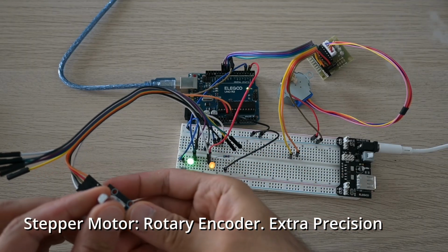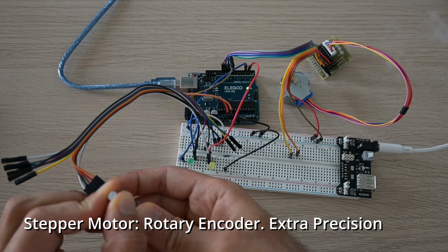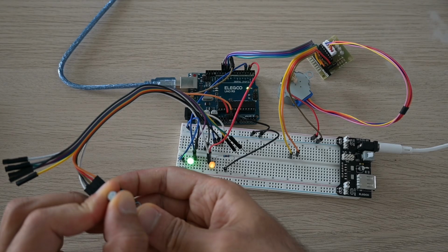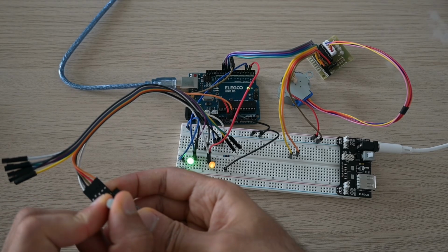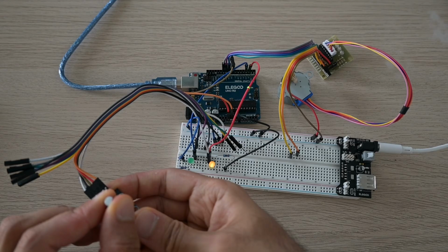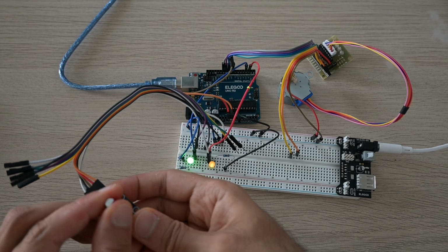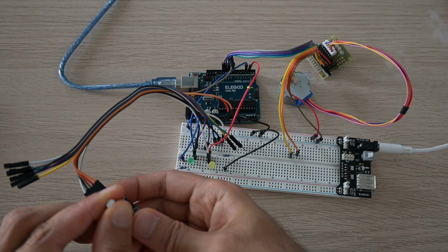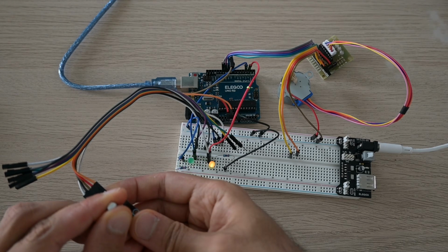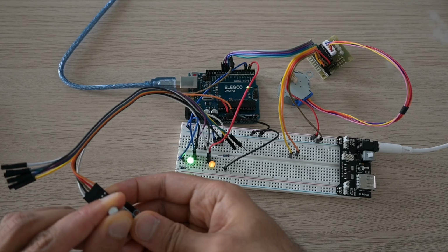To fix the previous behavior, this setup will use a script that takes into account all the movements from the rotary encoder to establish a target rotation angle that every cycle the stepper motor will correct itself towards. But first, the rotary encoder is not controlling any logic, and it's directly connected to these LEDs, just for demonstration purposes. Notice that the two LEDs are lighting up as the rotating encoder is manipulated, so that we can see which signals will be captured by our script. These signals consist of a predictable gray code sequence that lets us perceive with high accuracy whether it's rotating right or left.